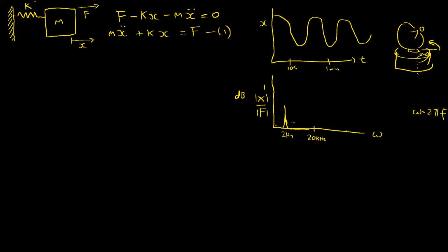And this would be it. This signal only has a frequency component at 2 hertz if it's a pure sine wave. This signal has no component out here, and it's just here. So we know that this is a sine wave at 2 hertz. A square wave would have harmonics, so we'd get extra peaks. So you can actually tell a lot about the time domain shape of a signal by looking at its frequency domain.